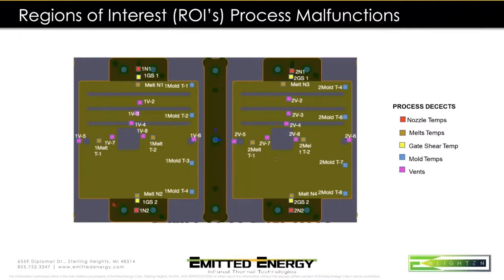Okay. We have a two-cavity plaque tool here at our R&D center. We'd love to have you all down here. We can teach you all about the thermal cameras, how they work. You can see it in this mold that's sitting right in front of you. This mold itself has several things that we can play with. It has inserts for, it's a two-cavity sequential valve, 4 drops. It has interchangeable gates that will give you from 40 to 60 to 80 thou thickness of gates.